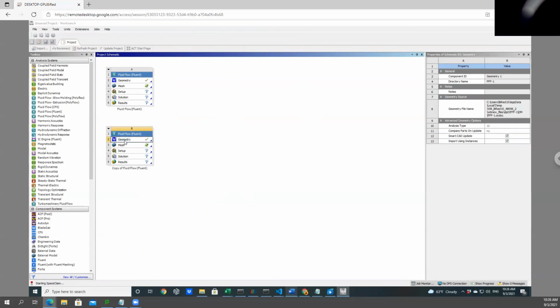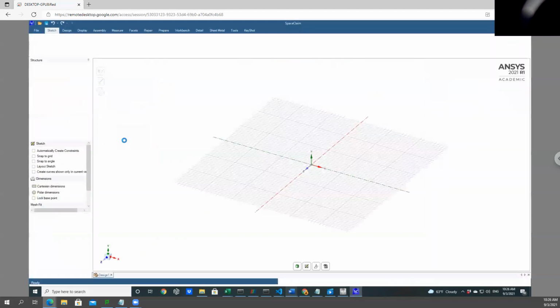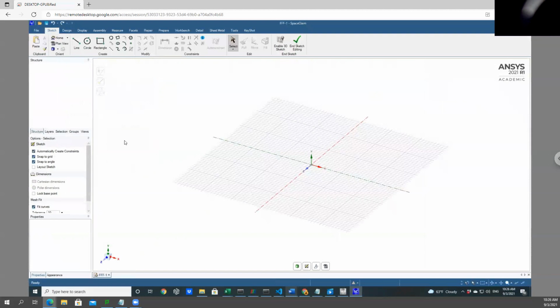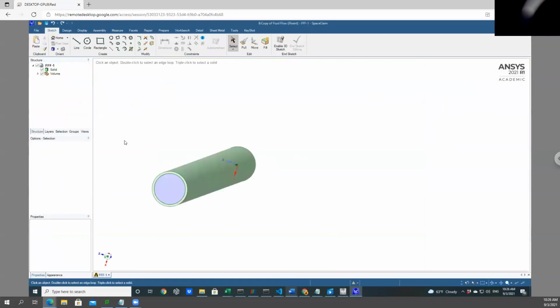If you have a very complex simulation, I strongly recommend you simplify it and first do the simple step, right? If you are able to do the simple step, then go one step more, a little bit more complex. If you are able to do that, then you go further, and you continue doing that until you have your complex simulation running.